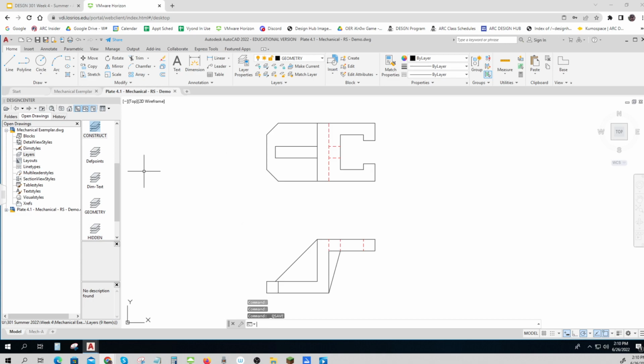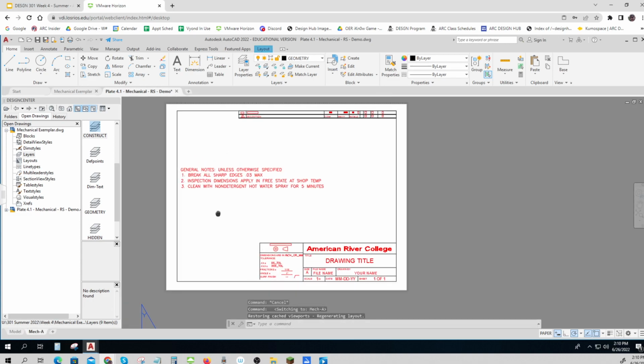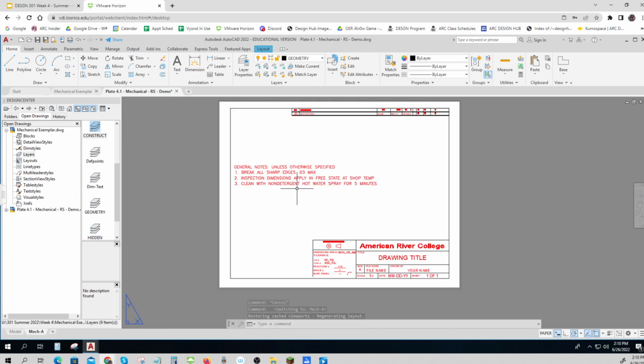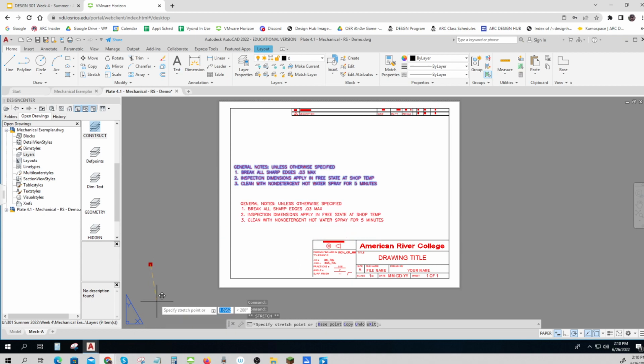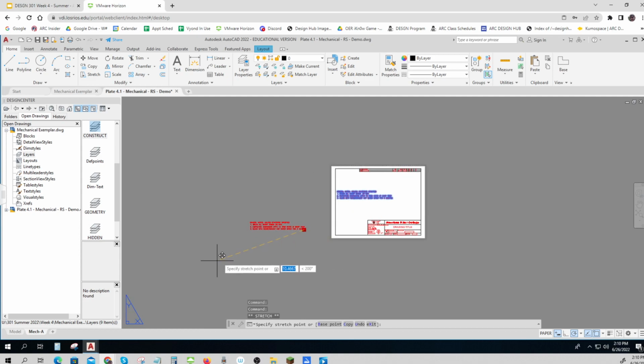Okay, so go to Paper Space, select the depth points layer, create a viewport, set the scale at 1 to 1. This, I might need to do something with this. I think it's going to be in the way. So I'm just going to get it out of the way for a moment, and I'll show you what to do with that in a little bit.